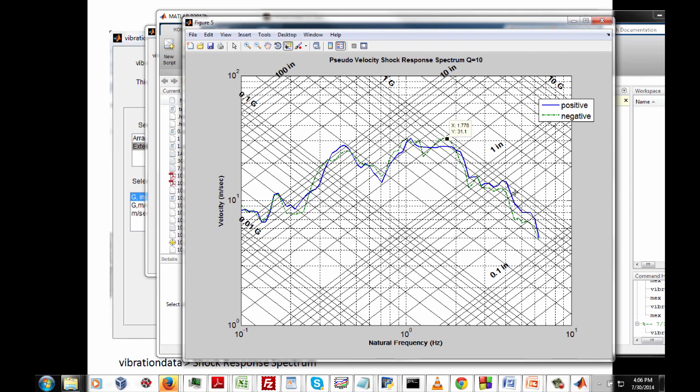Well, it looks like our peak accelerations are, there are 2 points that go a little bit above 0.9 g, and just for conservatism, let's round off to 1 g. So we might say that 1 g is the equivalent body load that we need to pass on to the static structural engineers.